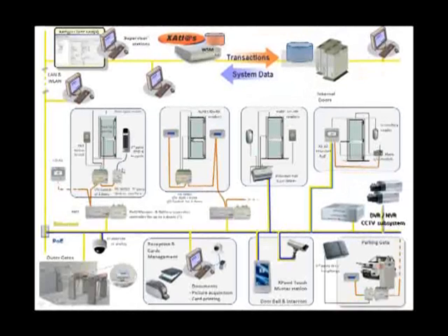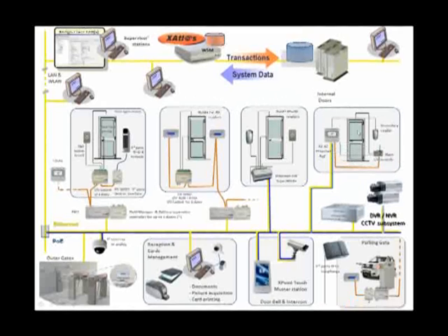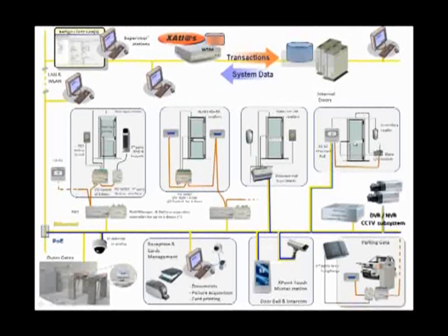If you have third-party readers, they can be interfaced with specific modules, or you can have the most integrated solution with X1, X2 that could be the single manager of a door, of a gate, directly connecting the activation of the lock or the sensor, or more securely, like in this picture, using a slave I/O module in the secure zone, which is the one that really controls the physical I/O with the gate.